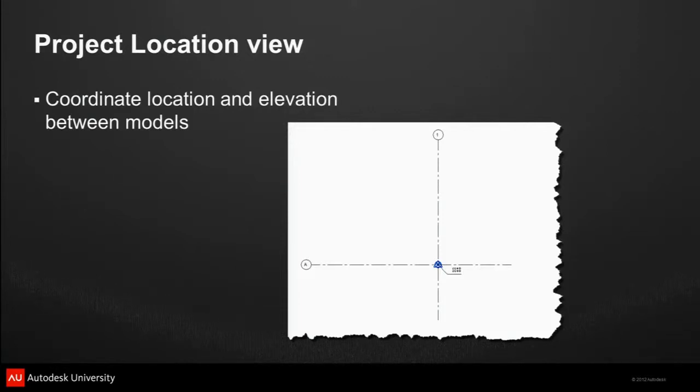This is a clip from about 1.5 years ago, actually, that I have. Don't have grids in your project if you're doing analytical import and export. Learn it the hard way, right? Import an analytical view, and it's got grid 1 and grid A already in there. It starts naming after that, hey? 2, 3, 4, 5. Doesn't match.